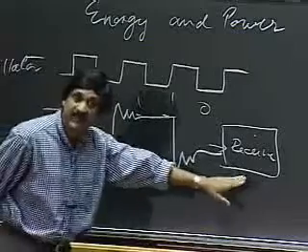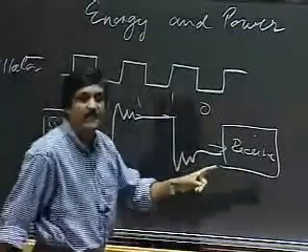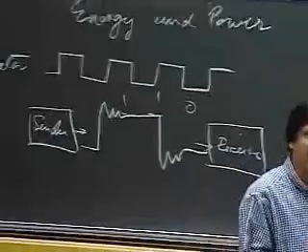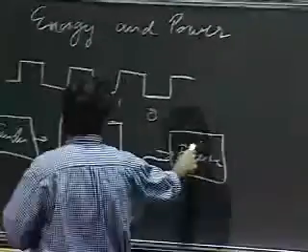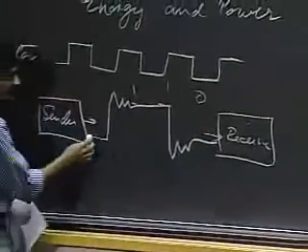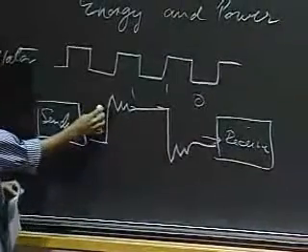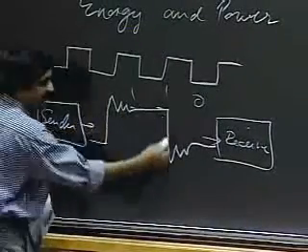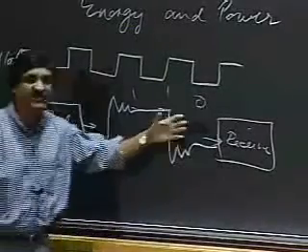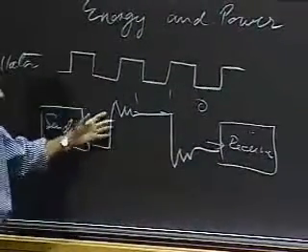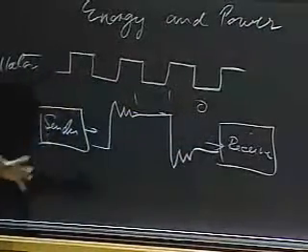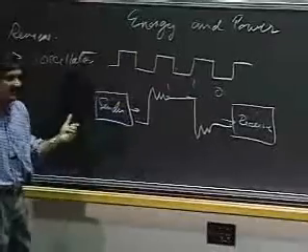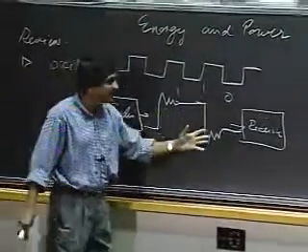But if I'm a receiver, I'm going to look at the square wave. There's no such thing as sending a 1 on a wire. You can't send a 1 on a wire. You send a voltage signal or a current signal on a wire. So the receiver receives a voltage signal. It's going to be 0 for some time, and then maybe 5 volts or 3 volts or whatever is your high, and then 0 again. So how does my receiver know it's a 110? Why can't it be a 11111000? It doesn't know. How does the receiver know it's a 110 sequence and not 50 ones followed by 40 zeros?